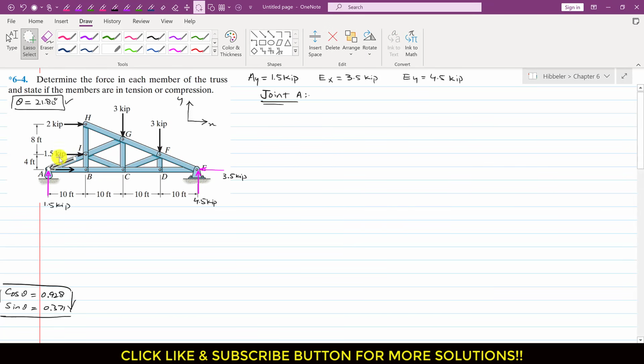If I draw this free body diagram here, I will represent these forces by their names. Instead of writing FAI force, I will only write AI. This will represent the AI member force, and this will make our life easier, so we will not need to write this F with each and every force.